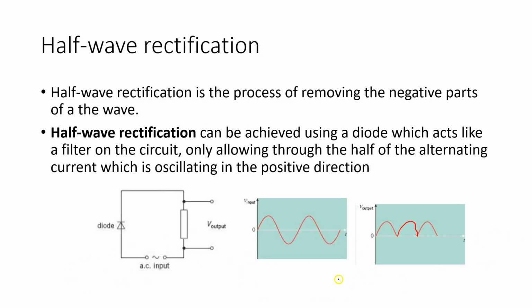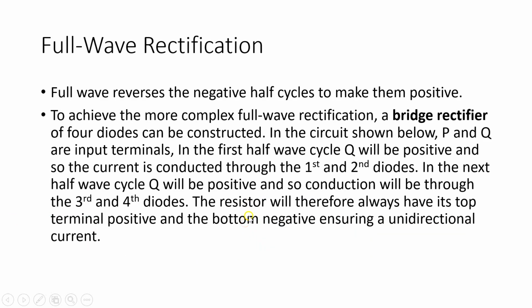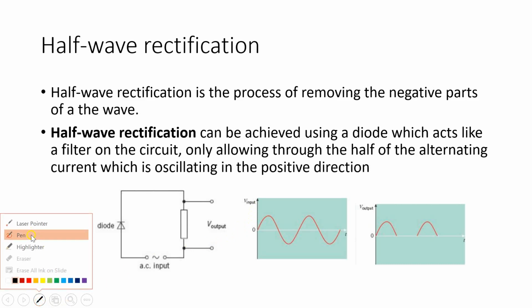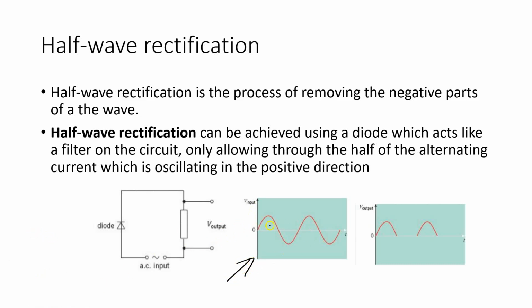Now, you will see on my next slide that this is what we call half wave rectification, right? Half wave rectification. So at first, this would have been your input wave. As I would have shown you, this is what you started out with. That's your input signal. Good? But because you are rectifying the alternating current, this is now what you produce. So you now produce a portion here, and everything here is now in the positive region.